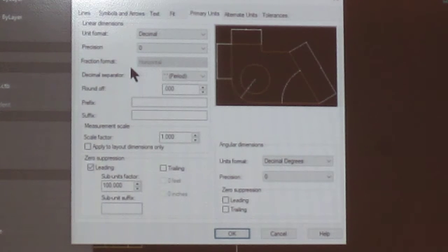The other thing I'm seeing, and this was 134 for the most part, but folks, I just want to clarify this. As your dimensions get smaller, I leave my text in here and I bring my arrows out. Okay? Now, I'm seeing, especially in the manual, I saw this a lot, where I'd see these little lines left in here. Okay, no, those aren't there. You pull the whole thing out. Remember, this is an 1/8 inch. We want an 1/8 inch at a minimum of this. Okay, CAD's going to do this for you automatically.